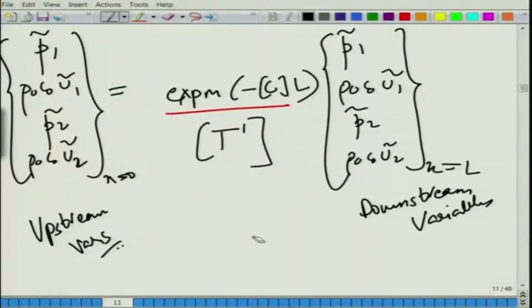Now, how do we go about using this information? That is what we have to see. Now, having denoted this matrix as T1, we probably would want to reshuffle a few things, because we are trying to follow the convention available in the literature regarding plane wave analysis of concentric or well perforated mufflers.